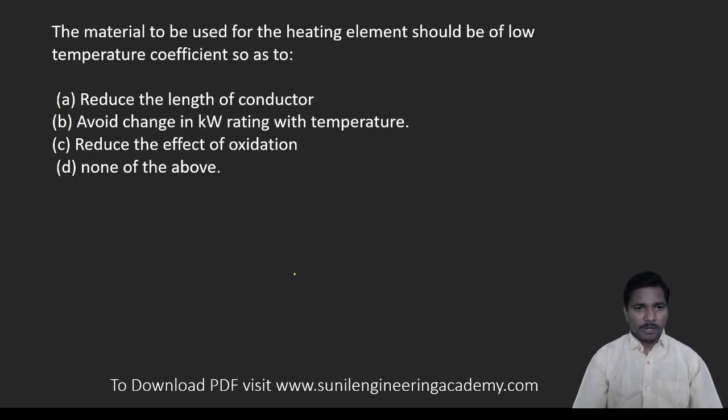Coming to the next one, the material used for heating element should have low temperature coefficient. Why do we need a low temperature coefficient? To avoid the change in kilowatt rating with temperature. We need to keep the kilowatt rating stable with respect to temperature. If the temperature is more, then the kilowatt rating changes again, and we may not get a perfect heat.